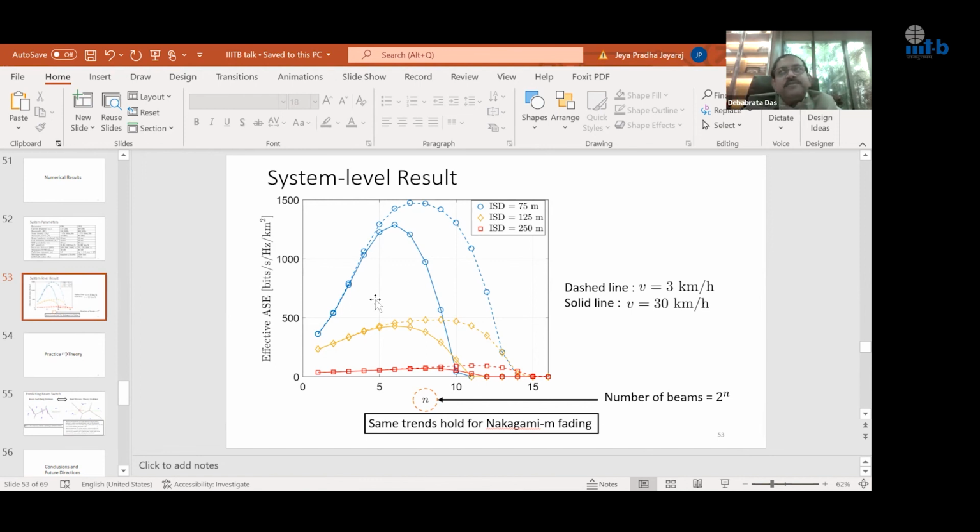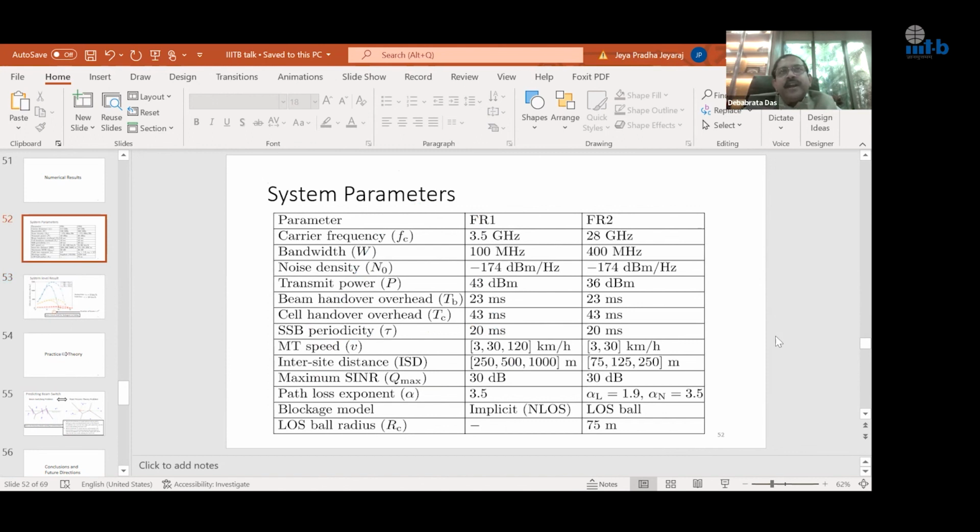In slide 52, you said that the internal antenna for the spectrum handover is around 30 milliseconds or 40 milliseconds. But ultra reliable low latency is expecting 10 milliseconds and below. And above the PHY layer, there is a MAC layer. The MAC, medium access control layer, has a scheduler, which also tracks the velocity of the vehicles. So do you think, from a system level point of view, because theoretically optimizations and delay reductions have been done, but the system takes its own time to hand over from MAC scheduler complexity to PHY layer spectrum, if 32 by 32 MIMOs are there. So how do you think it can be reduced? What are the research challenges?